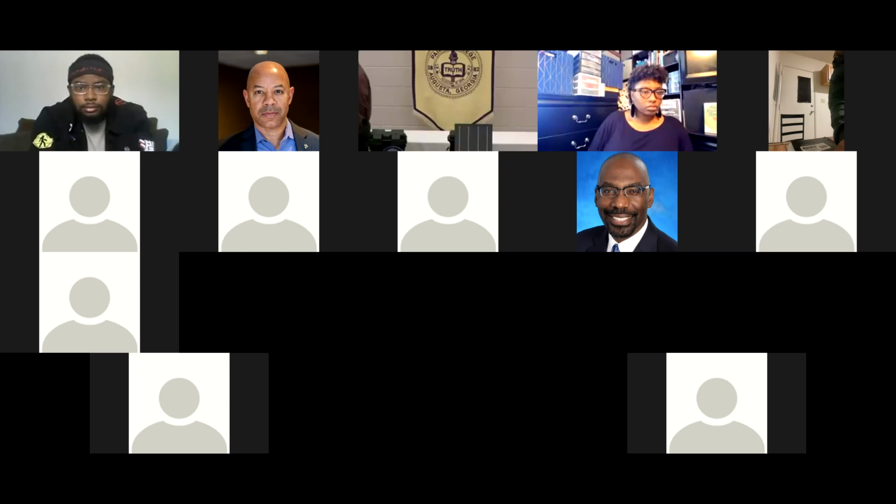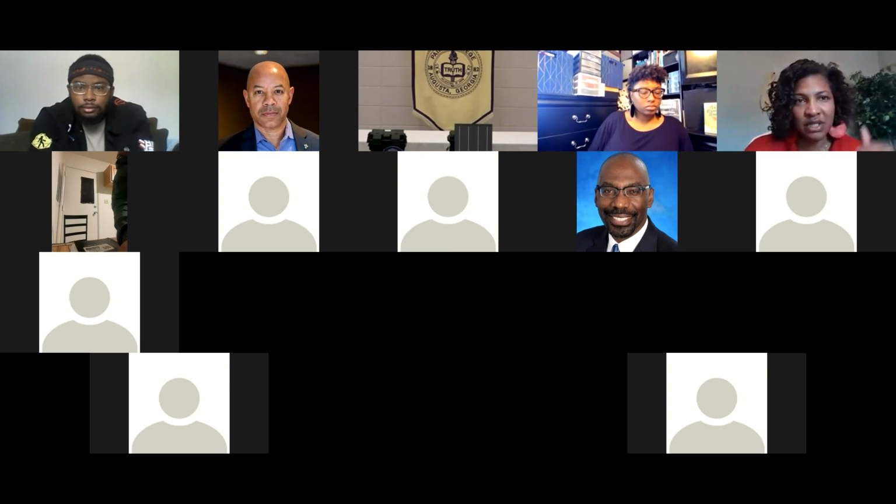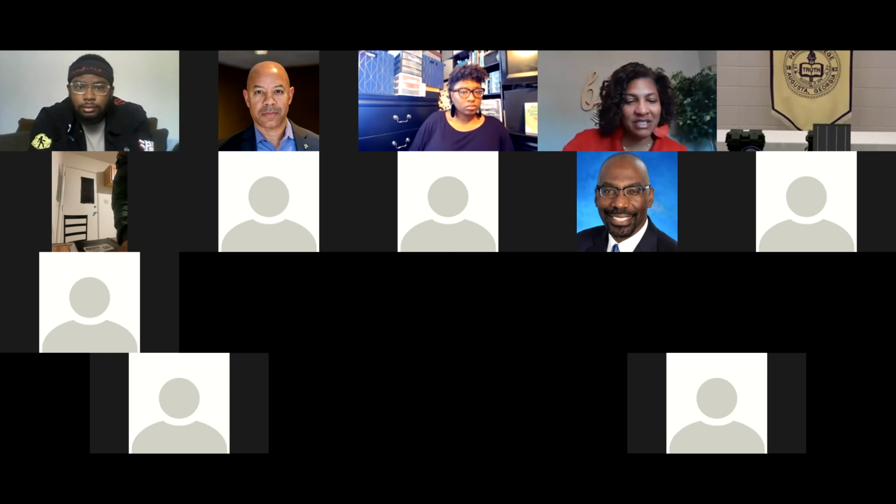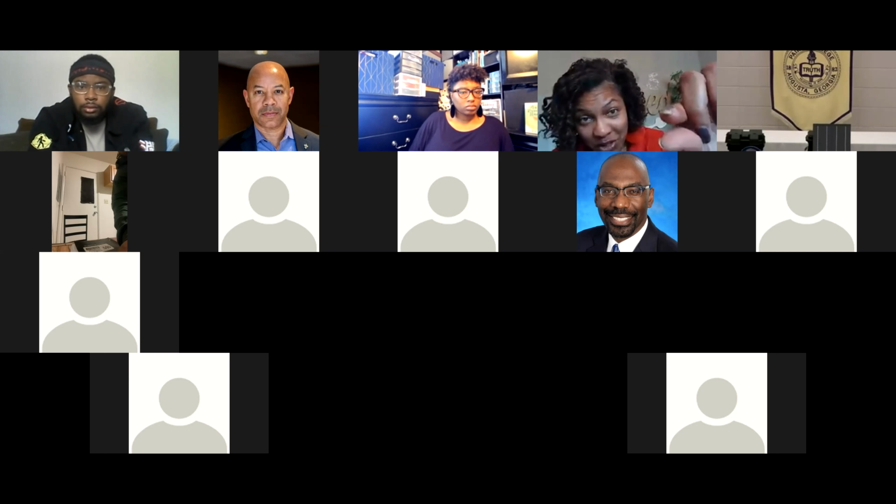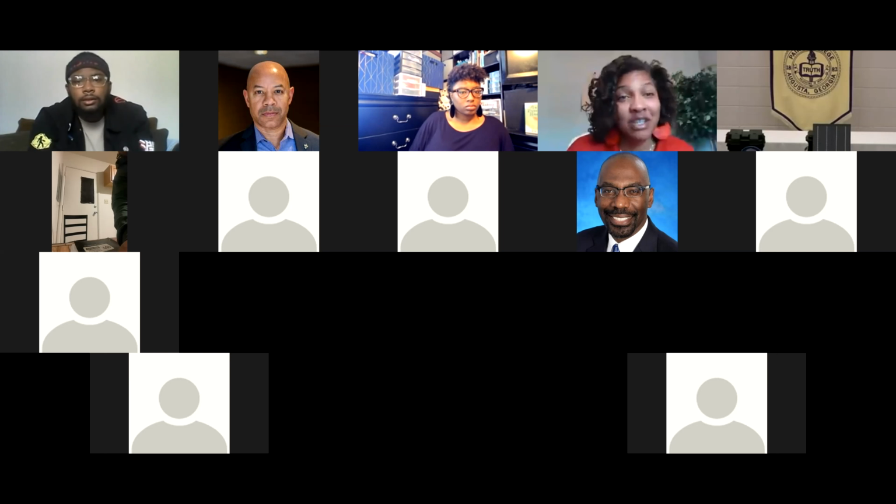Okay, so the floor needs to be flat so that once the vehicles are hovering over it, it does not... okay, so let me just give you an example. Let me turn my video back on. If there are dips in the floor and the vehicle is trying to ride over a dip area, if it's a dip that goes under, it's not going to be a problem. But once you have a dip that goes under, you got some of the epoxy that's going to rise, right? And once that rise occurs, if it's too high and the vehicle is only this far off the floor, but the dip is this high off the floor, then the vehicle gets stuck.